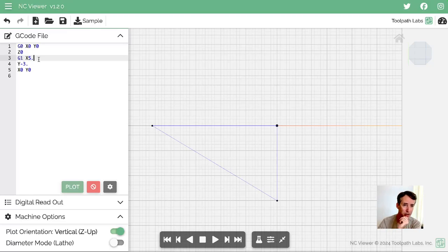One thing we're missing here, though, is a feed rate. G0 is just at a full rapid of the machine. You can turn down your rapids on your machine generally, but assume it's going to be fast. So G1, we can set to a feed rate. I'm just going to put like 20 for now. That's 20 inches per minute. That's just the rate that you're traveling through the material, or through your tool path.